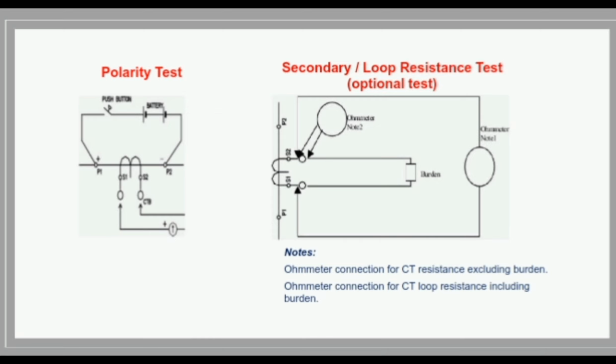Low resistance ensures the load is connected properly and the circuit is not left open. For the circuit connection for the secondary resistance, measure the DC resistance value and record. Okay, the same shall be done for all taps and cores. These values are influenced by temperature, so ambient temperature must be recorded during this test.